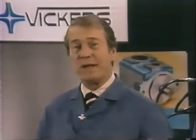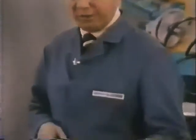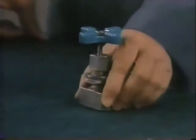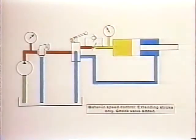A flow control valve, in its simplest form, is nothing more than a variable orifice. It could be as basic as this needle valve. By varying the size of the opening, we can vary the amount of oil entering the cylinder, and thus control its speed.